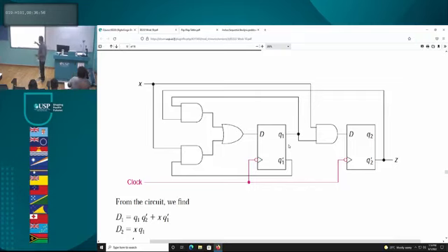What does the clock do? The clock ensures memory. Remember when we said in our derivation, whenever clock is 0, it's going to automatically go into hold mode or memory mode. So every time there is a clock pulse, every time you have a high going down to low, bang, it saves. It holds the particular thing. So that's why the clock is important. Right, what else did we discuss? There are 2 flip-flops, that means 2 memories being saved, 2 bits being saved.